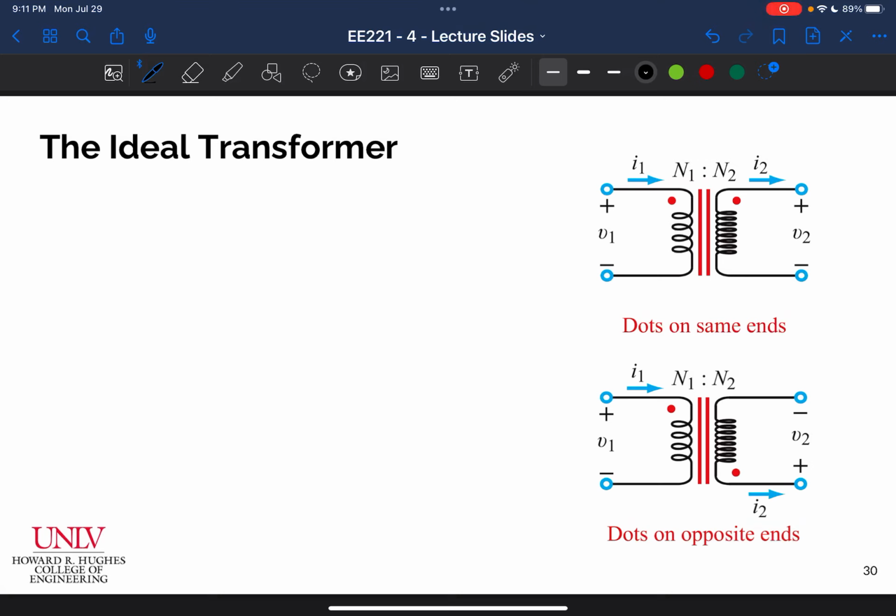All right, so now we're going to talk about the ideal transformer, which basically neglects those winding resistances that we talked about previously. Obviously, some things to note here. The ideal transformer is not expressed in terms of the mutual inductance. Rather, it's expressed in terms of the turns ratio. If you remember from the previous slides, we talked about how these N1 and N2 are basically telling us the actual physical number of times that this coil is wound around the core, right?